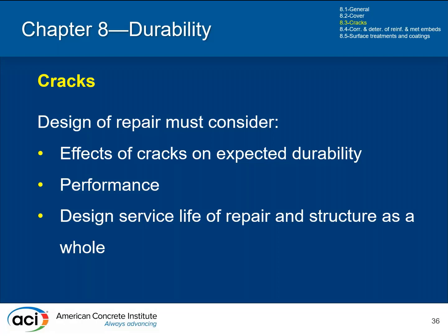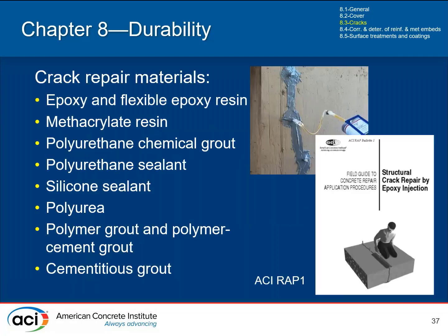And again, it's also different than in a new design structure, where you need to think about not just the repair, but the structure as a whole. What is the repair doing to the structure? What is the structure doing to the repair? And what's the condition of the structure away from the repairs, and how this cracking will affect all of these aspects, and figuring out the appropriate approach for those situations.